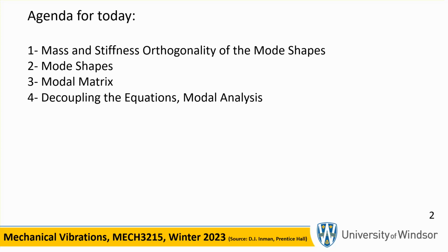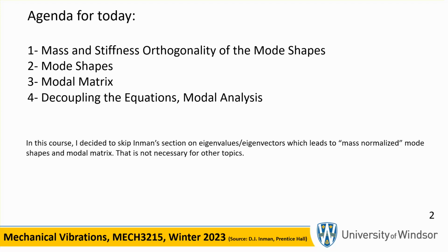So we want to discuss the orthogonality of the mode shapes, both in terms of mass orthogonality and stiffness orthogonality, and then out of that, we will be able to reach item number 4, which is decoupling the equation of motion, or modal analysis. Now, all of this may sound strange to you because you haven't seen it, but I hope that you have watched lecture 18 at least to have an idea for what is involved.